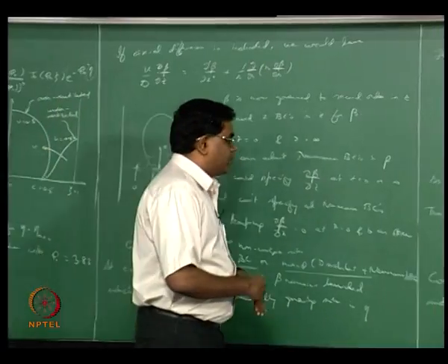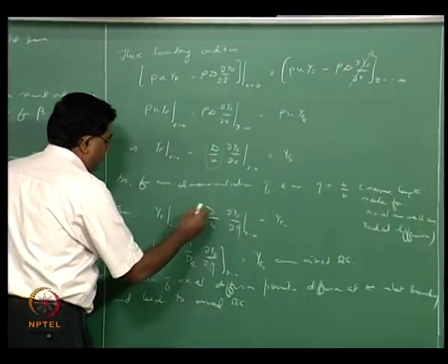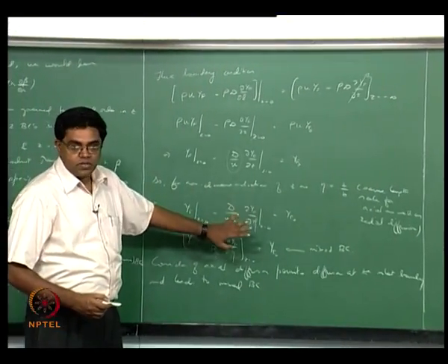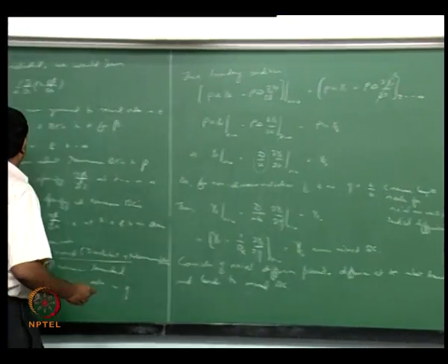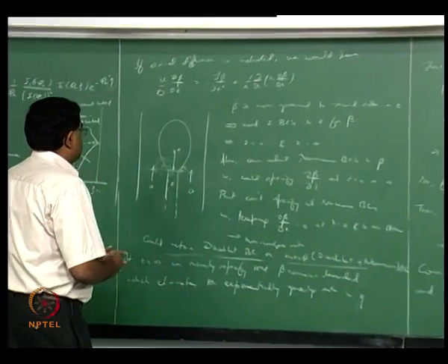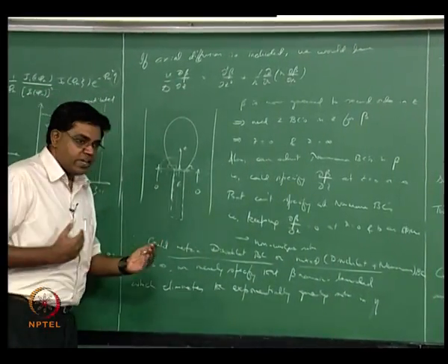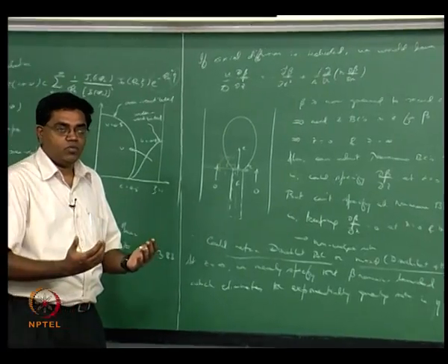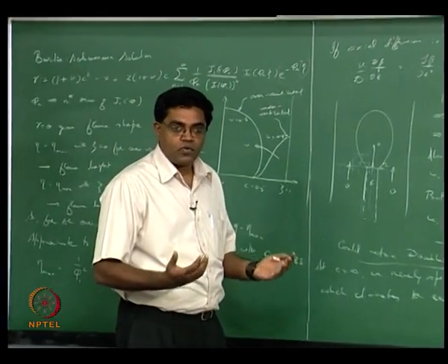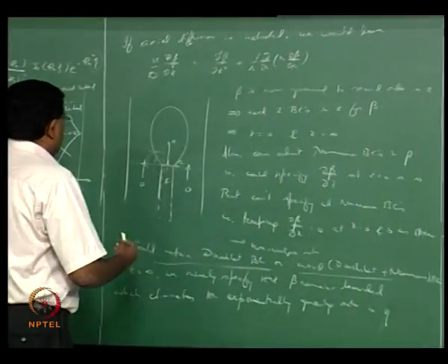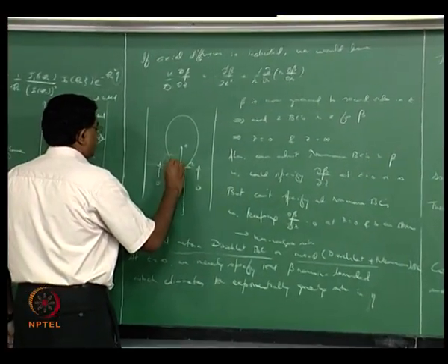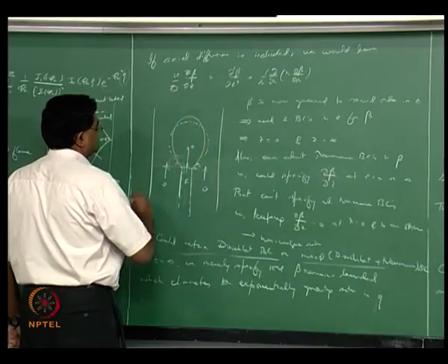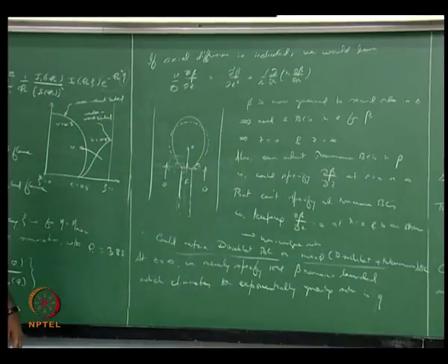So Peclet number here is obviously UB divided by D. This is the mass diffusion counterpart of Reynolds number that I pointed out yesterday, and what that means is at small Peclet numbers your convection is not predominating over diffusion. Okay, diffusion is quite important, and therefore you will now end up with a flame that's a bit fatter and shorter, right?